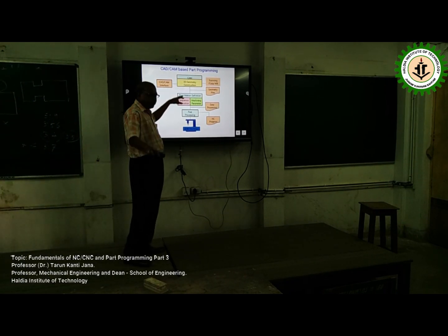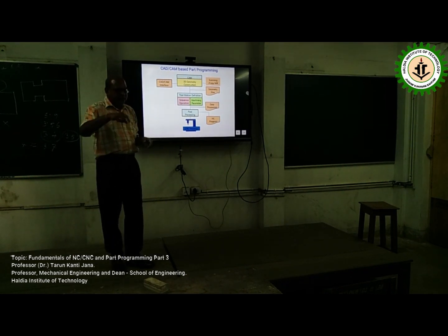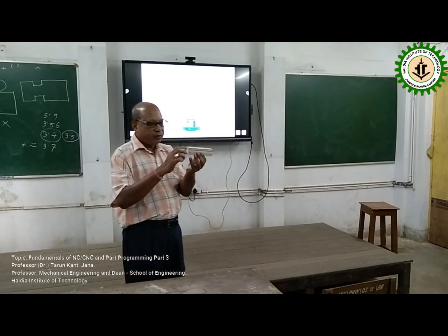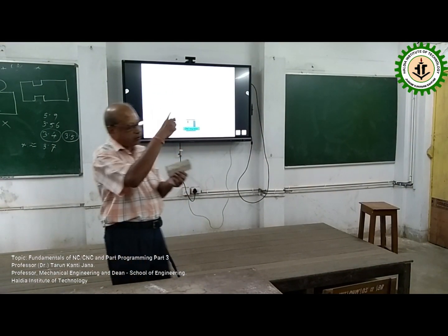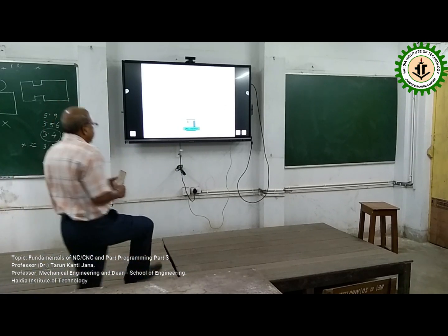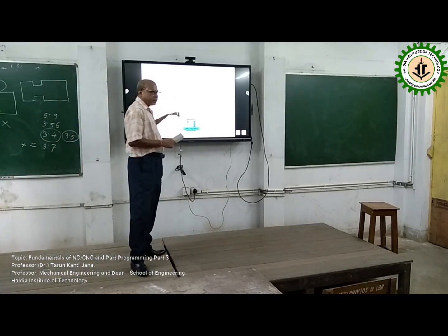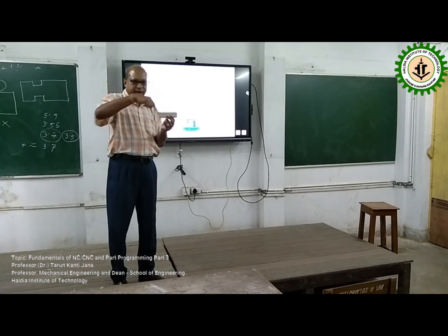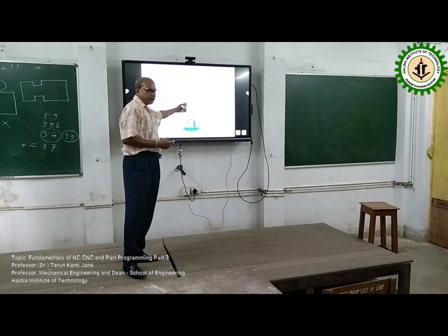From the geometry, through your mouse in interactive mode, you select the tool motion. You define that the tool is supposed to go along these 4 corners. Through the mouse you pick up these points and they show up by highlighting. Then comes the sequence of operation, as I told, whether you would like to move this way or that way. That is your sequence of operation.